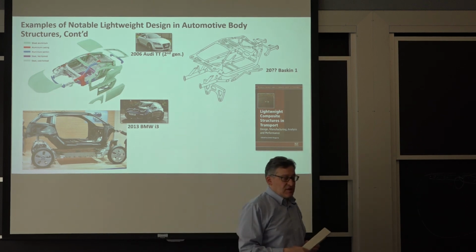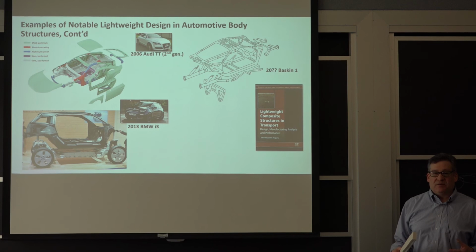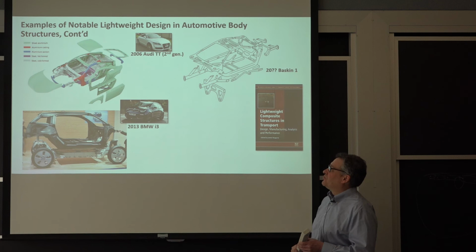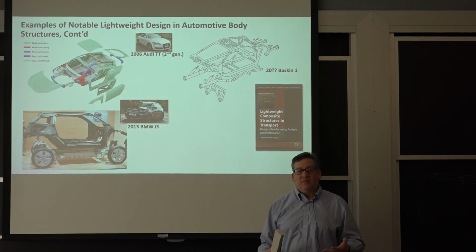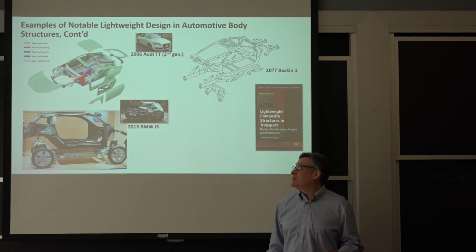This is one of the first cars, I think, to really do that en masse. The primary structural paths are made with high-strength steel, and then the closeout panels are aluminum. Now, there's a galvanic corrosion problem there, which I assume they solved. But it's interesting. They were able to produce this lighter structure by using aluminum where you didn't need the mechanical capability of a high-strength steel.